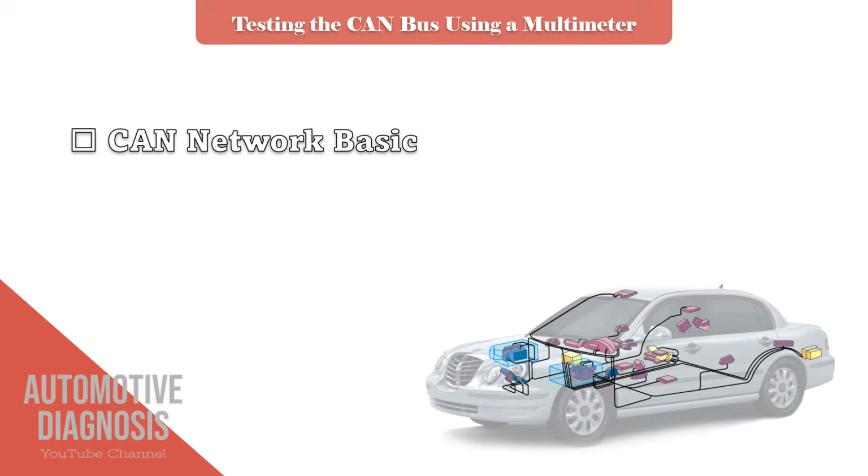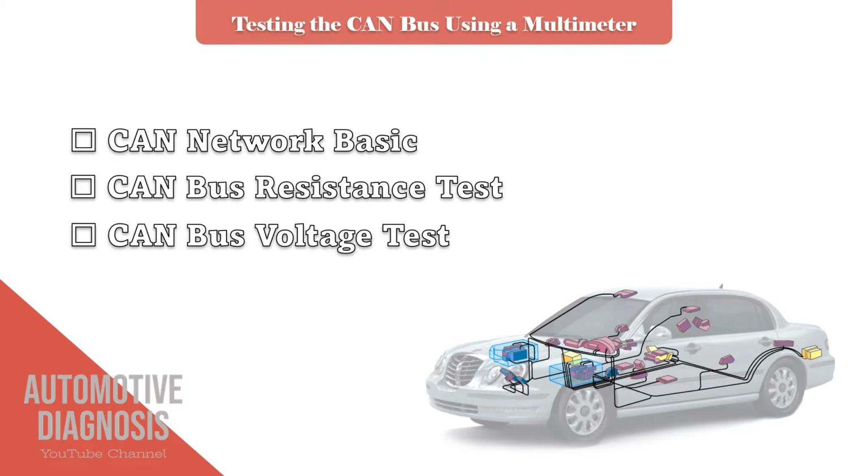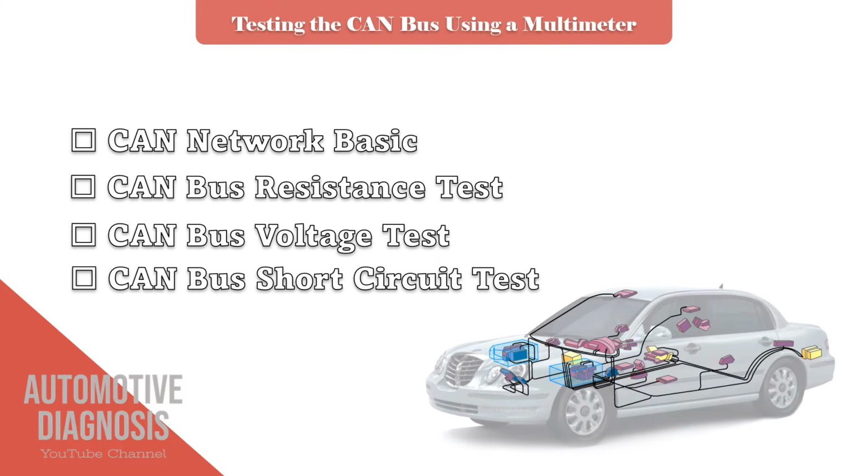At first, we will have a look at the CAN bus network. Then I show you how to test the CAN bus resistance. Next step is to check the CAN bus high and low voltage. And at the end we will see how we can test the short to ground. Let's start by CAN bus basics.